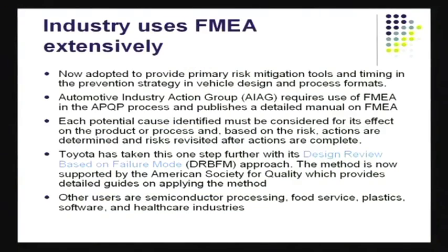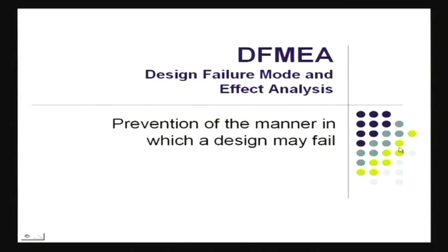Industry uses FMEA very extensively, and basically, this is something that is done very routinely, and has been prompted by the Automotive Industry Action Group, AIAG. They have prompted people to do FMEA, and you'll be doing design review. That's like another mode of doing FMEA, the design FMEA. This leads right into our design failure mode and effects analysis.